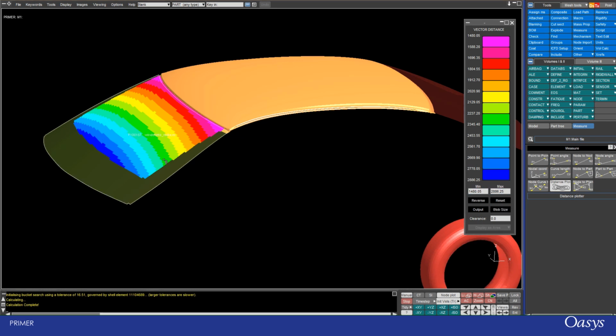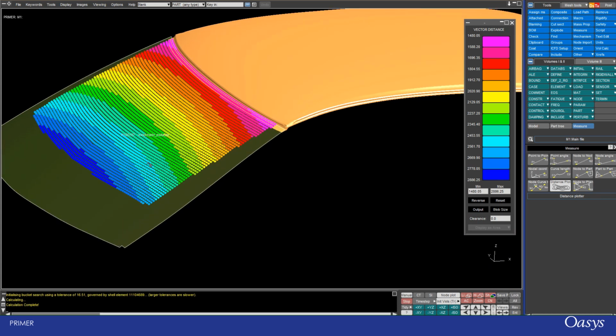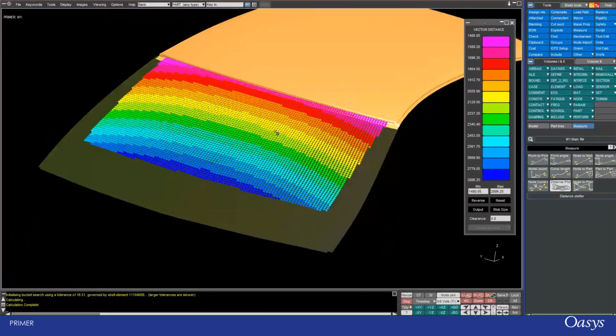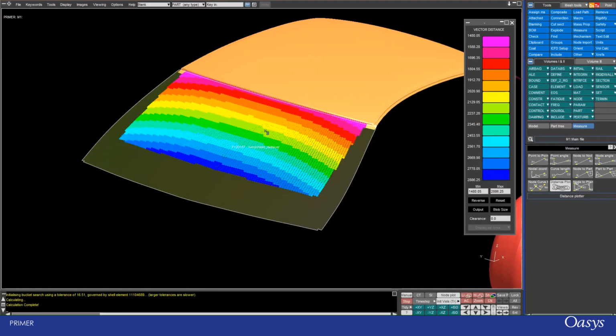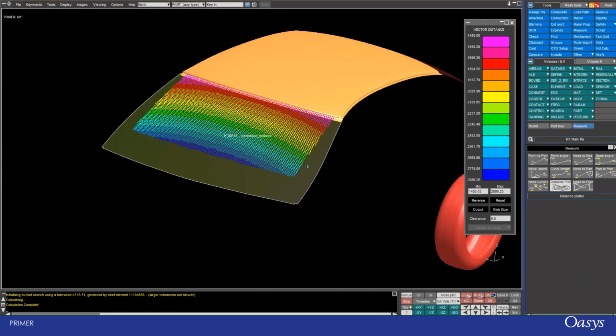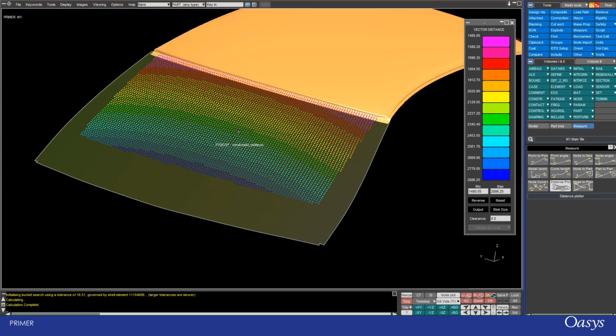Now what's actually happening here is we have some blobs that are being overlaid. These are graphical things that can be placed on top of a model within Primer and can be used to display additional information. So they're just colored in nodes essentially in space. And we can tweak the size of the blobs here. So if we wanted to make them say maybe number 5, see they'll shrink a bit. So that could be good if lots of our nodes are quite close together and so we want them to be a bit more visible.